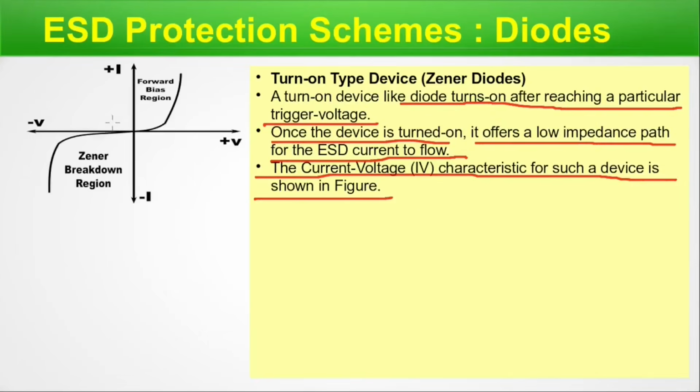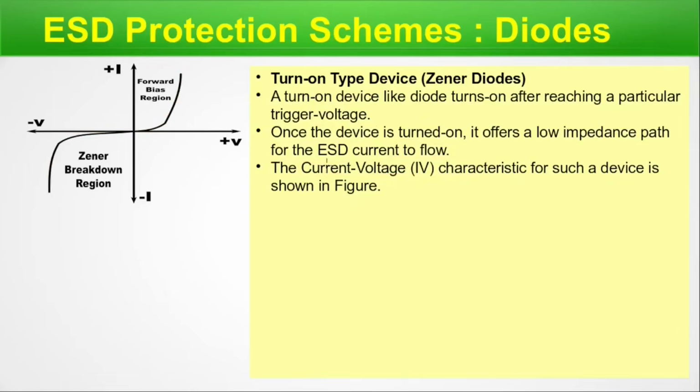So this is your typical Zener operation, forward bias. Here we are not talking about the forward bias. We are focusing on the reverse bias, and you can see if we draw a perpendicular at this particular VZ, we generally call this VZ. At that particular VZ, the breakdown will happen, right? At this point, it will offer a path where a huge amount of current can pass. So you can see I is here, minus I is here, and this type of protection scheme can be used in a typical ESD protection layer where the level is characterized by VZ of the Zener diode.